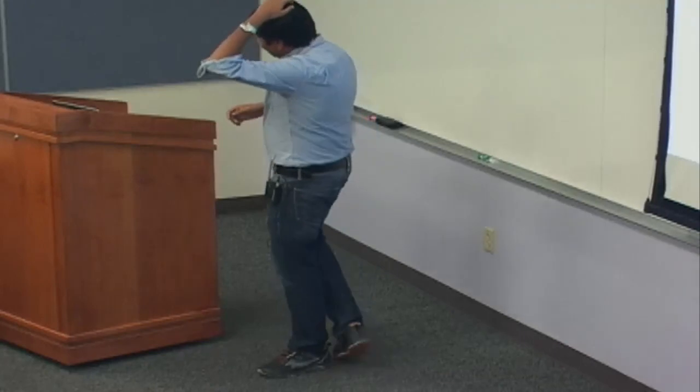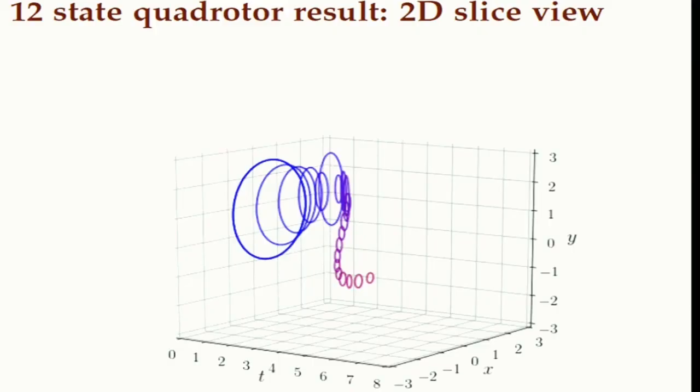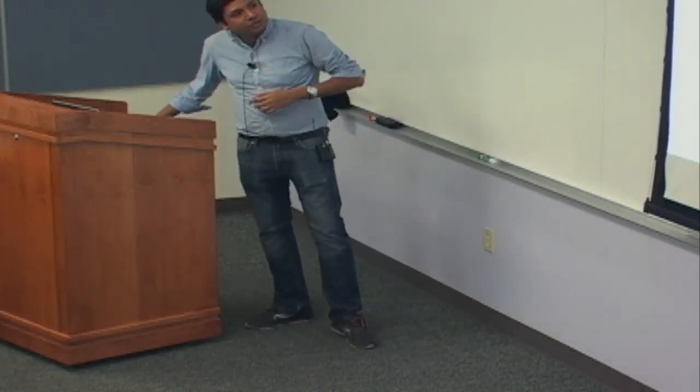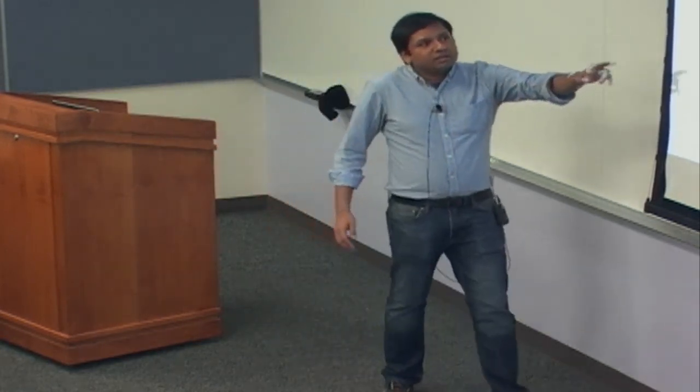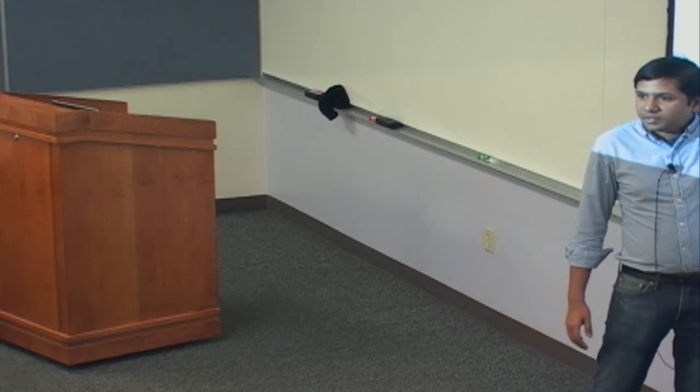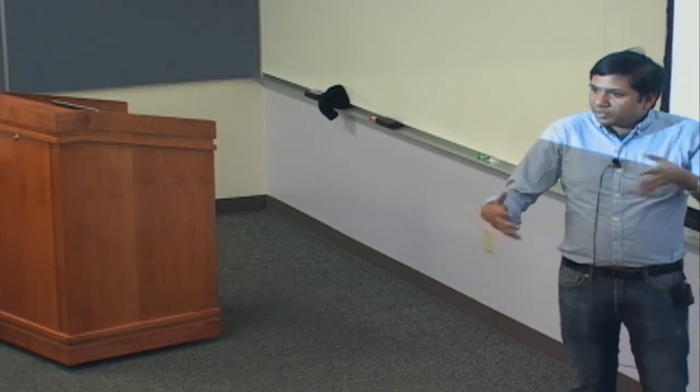Because the uncertainty is time varying. One thing is that it is smaller because there is a controller in the loop, so it's stabilizing, number one. Number two, you will see that sometime in between it grows and then it shrinks. That is because of the uncertainty description in the wind that I've shown. These are time varying, not constant. So you're assuming the wind gets nicer over time? No, wind can fluctuate very much. Think of it like a diagonal matrix times sine t or cosine t. Okay, so wind can fluctuate. Wind can get strong over time or it can decay over time. Okay, yeah.